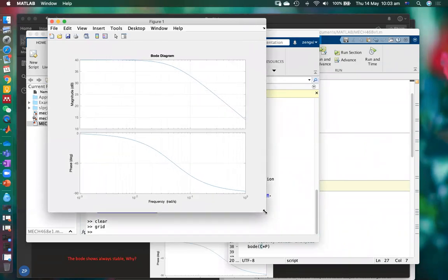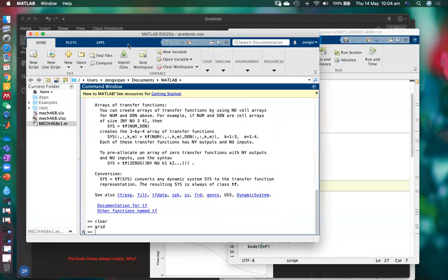Like we mentioned, for the system to be stable or unstable, we look at the phase margin. So in this case, we look at when this crosses 0. It's kind of on the right-hand side, a little bit over here. It didn't plot the whole range suitably. But if you look at the phase here, the smallest phase it gets to is negative 90 degrees. And remember, our phase margin is this point minus negative 180. So no matter what, we will have more than 90 degrees of phase margin here. That's why we don't have any potential to go unstable. The system is always stable and always has no overshoot, because it's only a first order system. The worst case the phase can go to with a first order system is negative 90 degrees. So that's the first thing we mentioned.